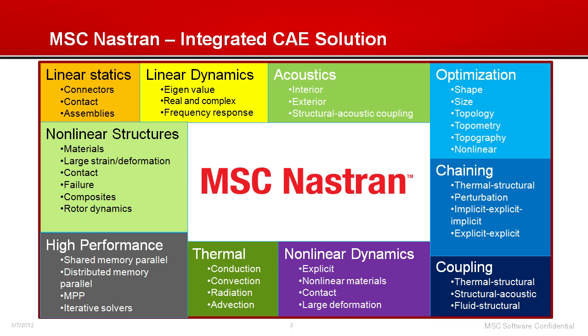This could be, for example, doing a thermal analysis followed by a structural analysis, or it could be a nonlinear static analysis followed by a nonlinear transient analysis, or it could be a co-simulation of a thermal mechanical structural analysis. So that is what we call the coupling analysis.